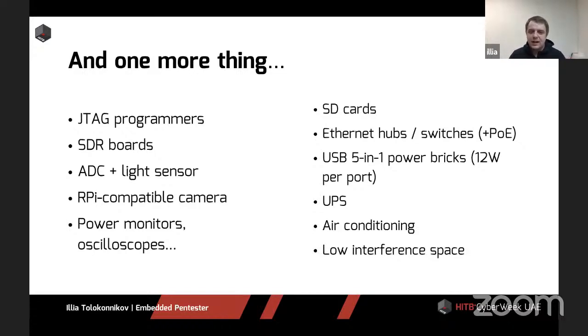With that kind of setup, with the ADC connected to the Raspberry GPIO header, you can even run tests that measure brightness levels. If you have a device that changes brightness level somehow, just calibrate those levels to different ADC readings or ranges, and you can do that.